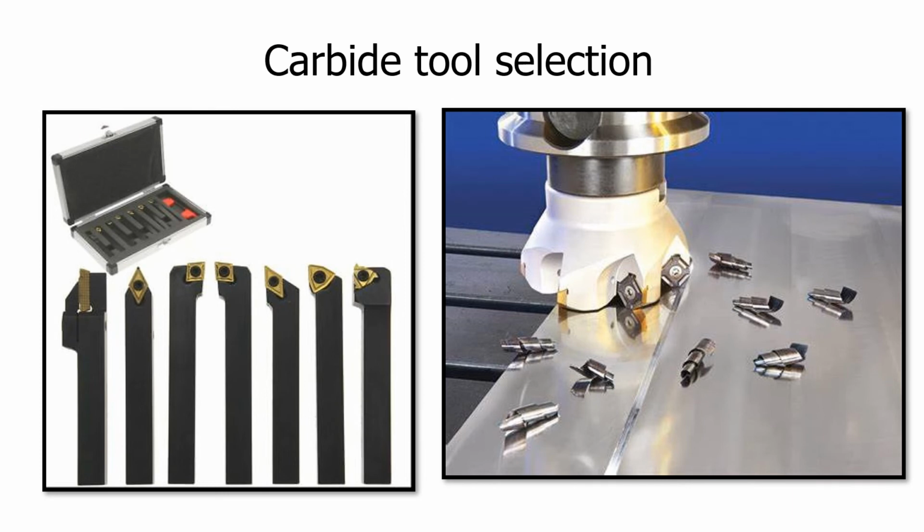There is no doubt that indexable throwaway inserts are convenient and efficient, and now cost effective, as it eliminates the need for large tooling inventories or specialist sharpening machines or personnel. One tool holder can accommodate inserts for various operations and materials. This goes for milling, drilling and turning. Depending on the configuration and orientation of the insert, some inserts can have up to 8 cutting edges.